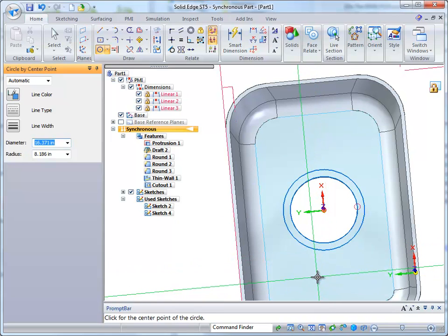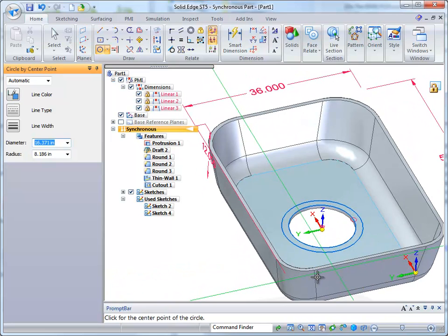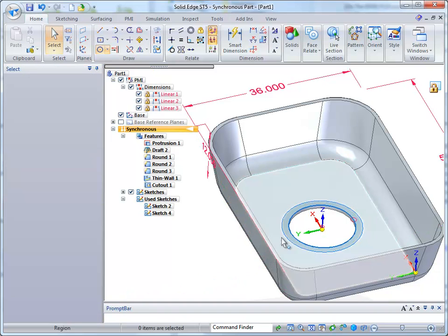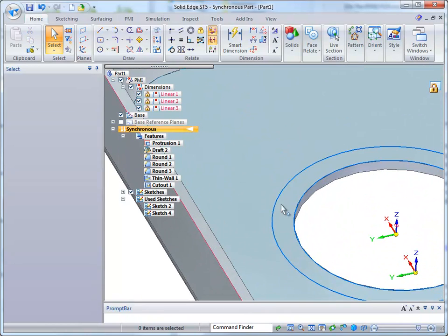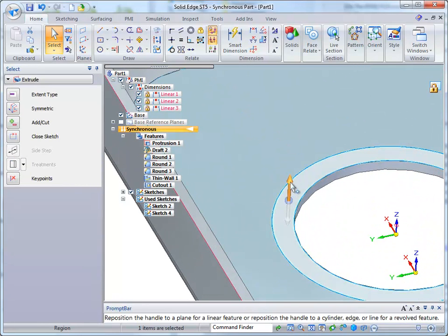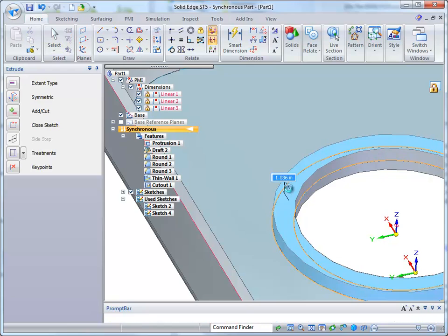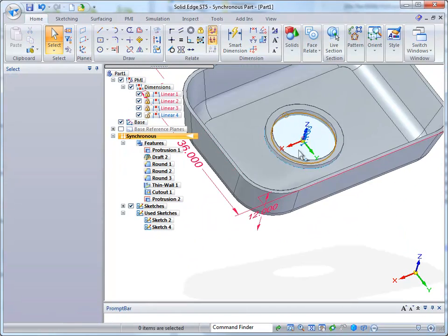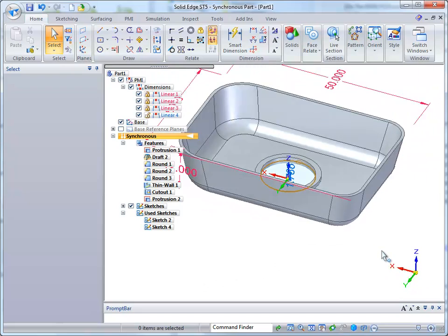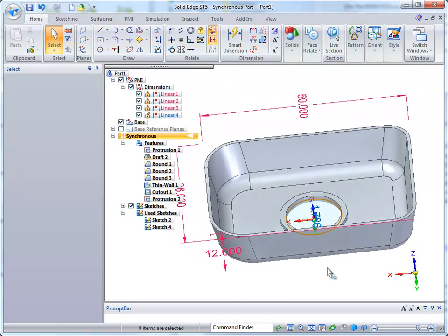Now, I'm not sure if I really had to do all of that or not. In SolidWorks, I could have reused the original sketch and used the thin feature with material to the outside, but I just pressed escape, click inside the region between these two circles, and pull some material up. Now, I just wanted to create a lip around the hole. That was all I wanted to do, and so that's been done.